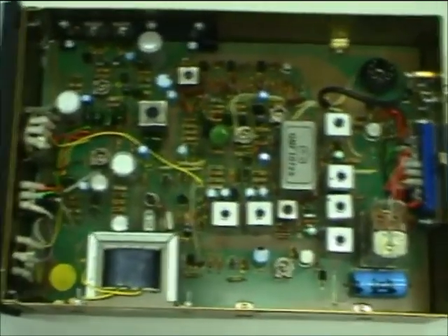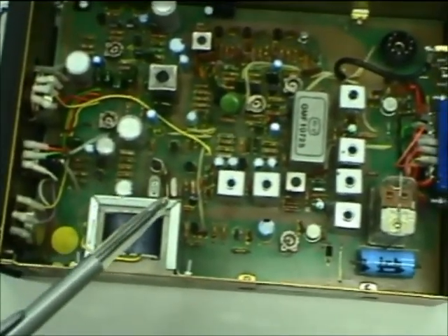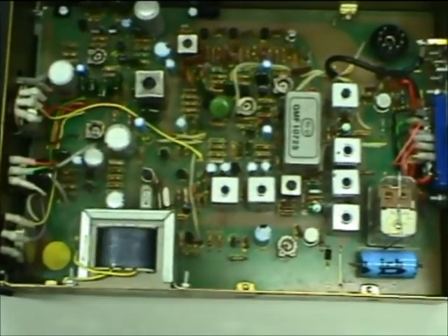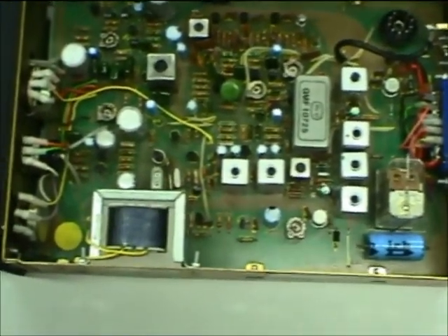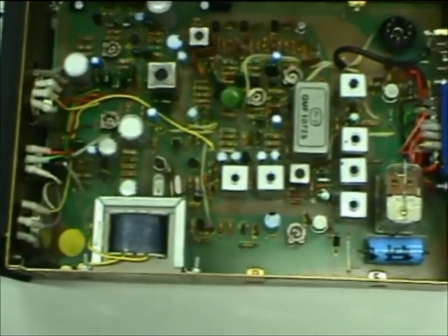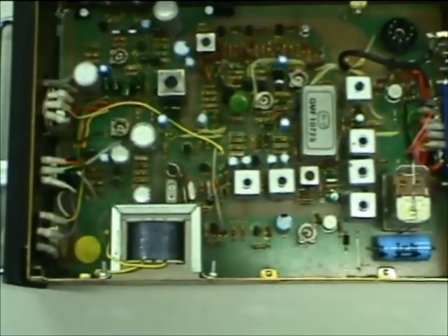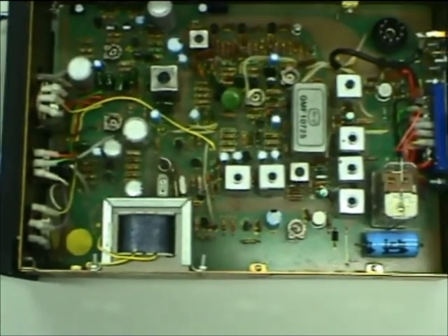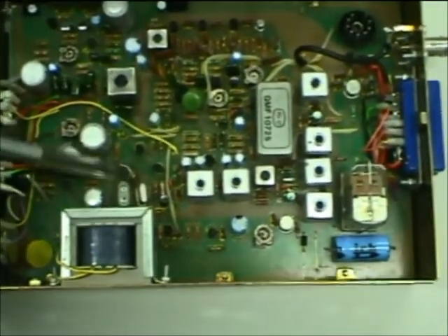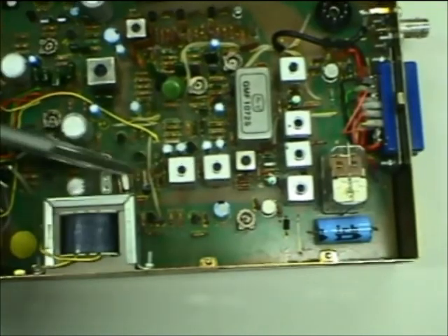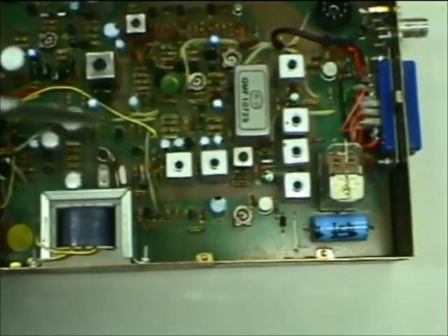Now the local oscillator is along this way here. It uses a quartz crystal because it only has to work on one signal frequency. You can do that in receivers. If you only want to work on one fixed frequency forever and a day, you can keep it nice and stable without having to retune all the time. Use a quartz crystal oscillator arrangement. That's the local oscillator chain here.